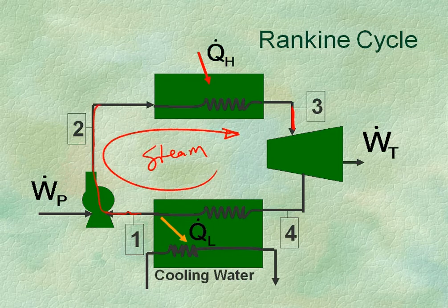Technically we have a superheater here too, so this is a boiler and a superheater that will really use some of that Q to superheat the steam too before we put it into the turbine. So we'll have the liquid pumped up to that high pressure so that when you do turn it into a vapor, it's got a mechanical potential pressure.